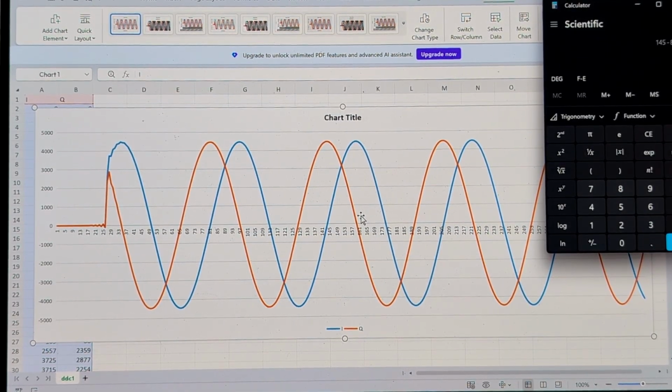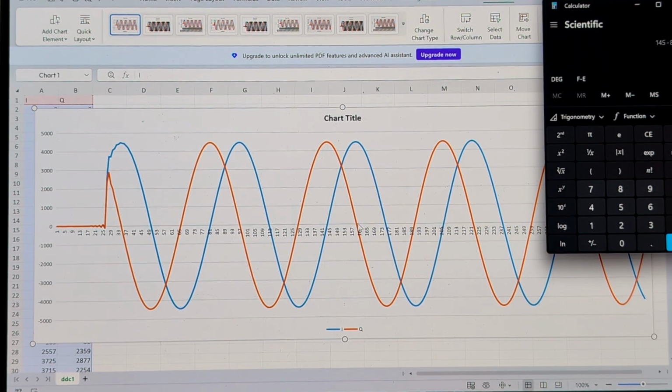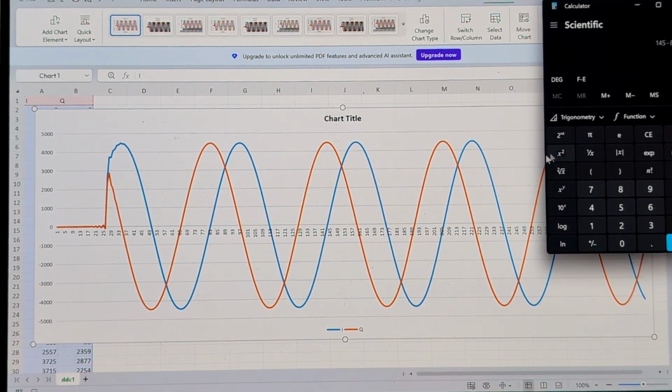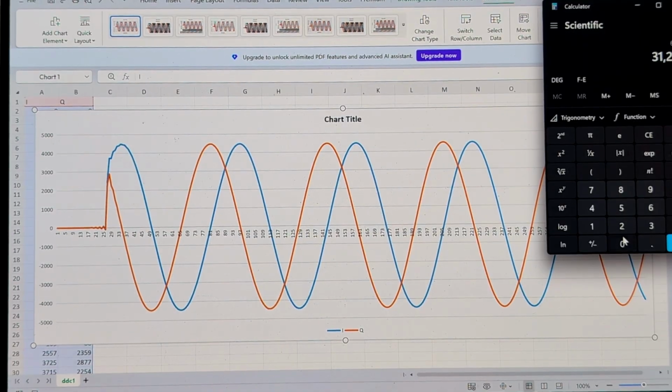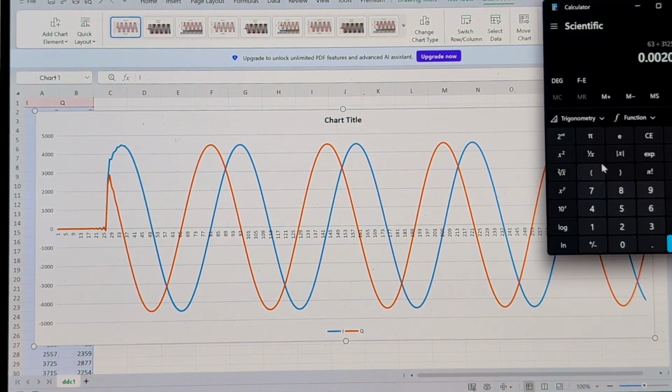Now these steps are at the output frequency of 31 kilohertz. So it's 32 microseconds between steps here. So we divide this by 31250 and take the inverse, 496.